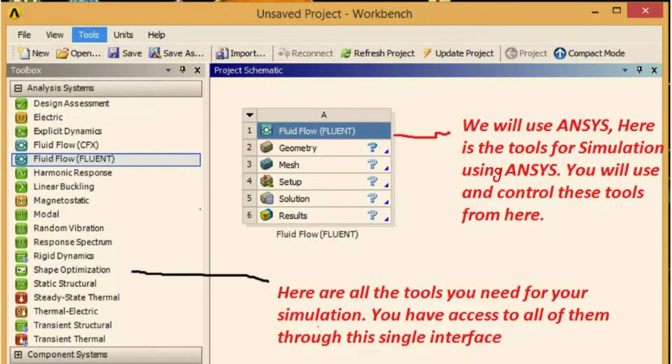The thing is that if you want to change anything anywhere, that influences everything. So, if you are very smart, you can take some components, not all of this. I think you have to scroll down; I could not show all here. This geometry, mesh, setup, solution, all are different components. You can put down a geometry and then connect it with one mesh, with another mesh, and a third one. So, you can put a lot of things together. If you change one, that will not alter your whole setup. So, if you want to do a parametric study, say a couple of meshes, you can actually do that. We will show you this afternoon.